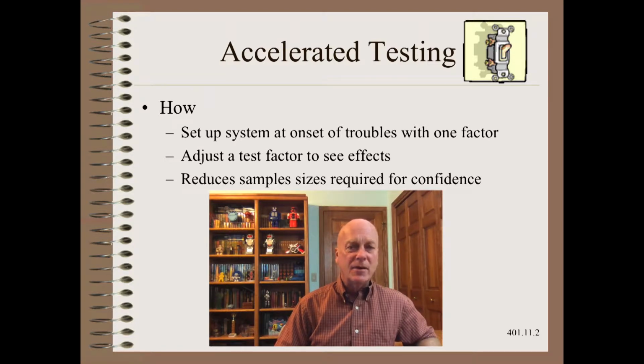In electronics, for example, test technicians may apply simultaneous vibration and heat well beyond rating to intentionally increase the failure rate. This is not quite the same thing as the exaggeration tool we discussed earlier. We aren't exaggerating the knob we are studying, rather a different one, so that the failure rates are convenient to study. If the rate is too low, trial durations are tediously or impractically long.